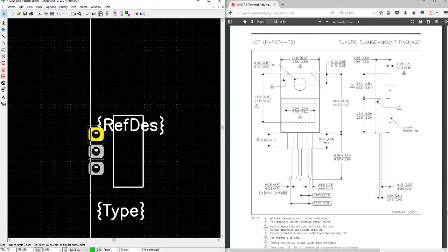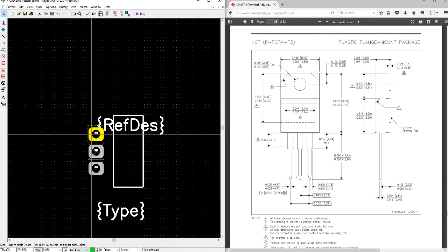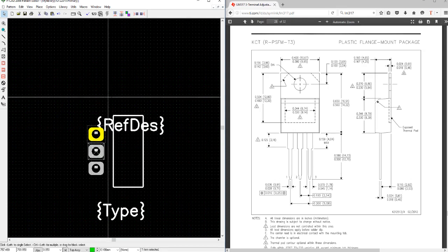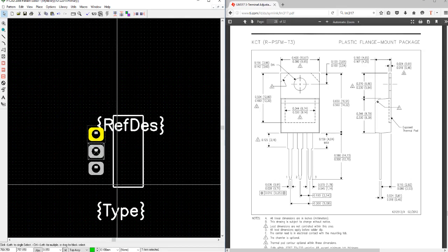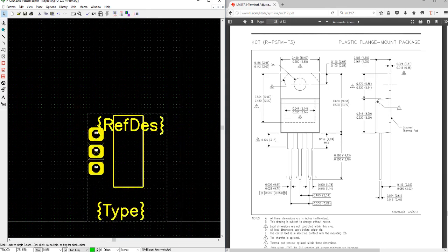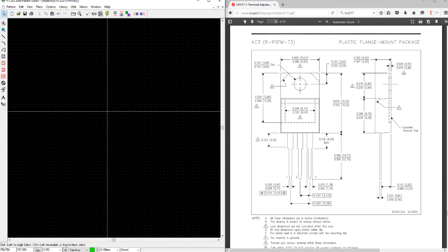There's some surface mount examples where I can more effectively show you the working of the pattern wizard. I just wanted to show you at least what can be done with pattern wizard, but from this example you can clearly see that the pattern wizard is not always your friend when you create your patterns, and you need to use the pattern wizard only when you can actually benefit from it. Doing it this way just wastes time. So you could have just gone and created this pattern manually by yourself like I did in the beginning. So this basically concludes the whole pattern creation.